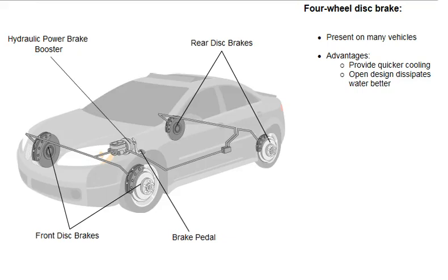Many new vehicles have a four-wheel disc brake system. There are several advantages for using disc brakes over drum brakes. Disc brakes provide quicker cooling, which increases their effectiveness and also dissipates water better due to their open design.